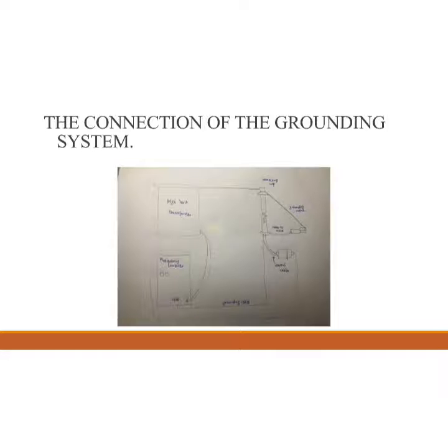Next, connect to the grounding switch. Based on the kit manual, it states that the grounding switch is used to ground the high voltage construction kit. Make sure that the connection is neat and tidy to avoid any accidents. The connection is then connected to the VM.